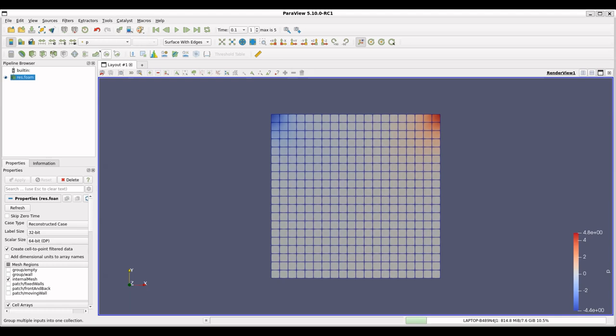I don't use OpenFOAM, but I'm using another open source software for doing the CFD analysis. It is called Open TELEMAC. When I extract the VTK files, my VTK file comes at different times. So suppose I run a simulation for 4 hours and I save the results every 15 minutes. So it will give me a VTK file for every time step that I have saved. So every 15 minutes there will be a VTK file.